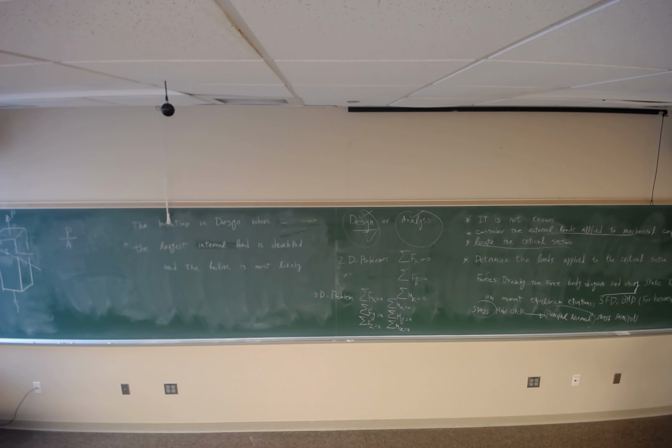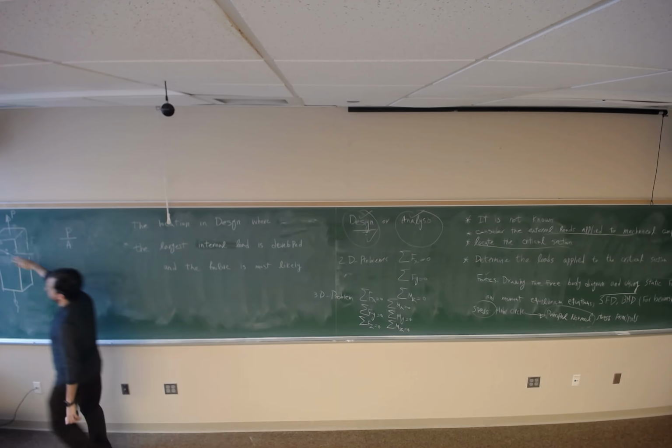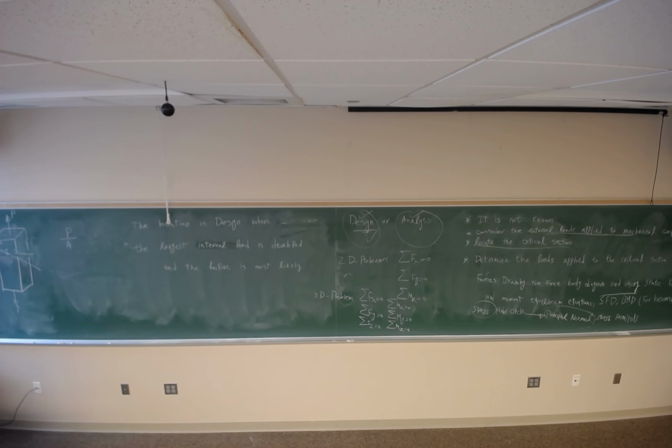I didn't change the load, I didn't change the size, I just changed the plane. So by changing the plane, I'm going to get a different stress. It's because of the definition of the stress, force divided by the area. The area comes from the plane that you define for passing through point A. So this is one important thing that you should know.